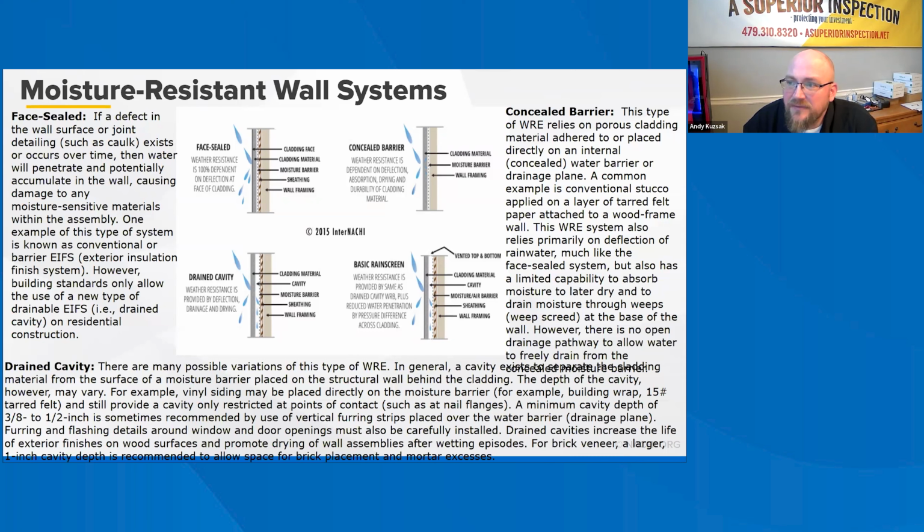In addition, selection of a siding system generally focuses on attributes such as appearance, cost, and durability. There are different types of cladding systems that protect a building from rainwater penetration and its accumulation in walls. This section is intended to show the home inspector the basic installations of the weather-resistant wall envelope as described in the 2006 IRC. IRC 703.1 says, exterior walls shall provide the building with a weather-resistant exterior wall envelope. The exterior wall envelope shall include flashing as described in section 703.8.